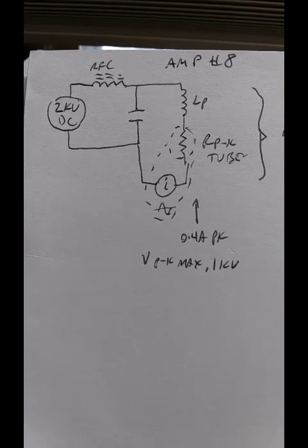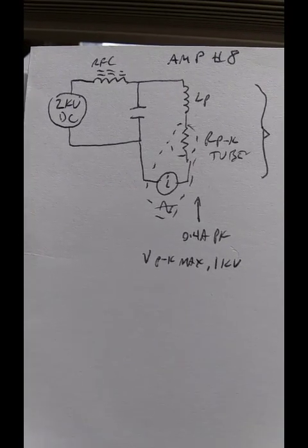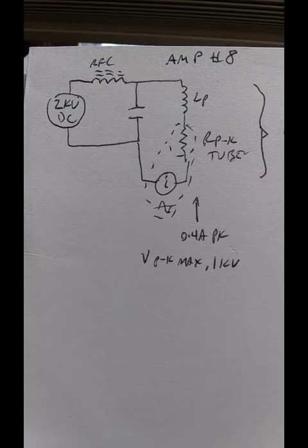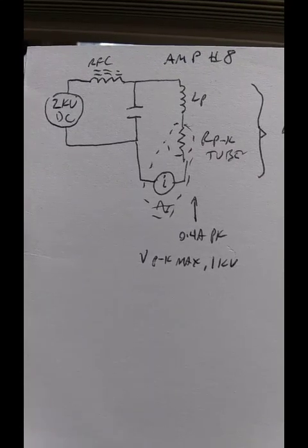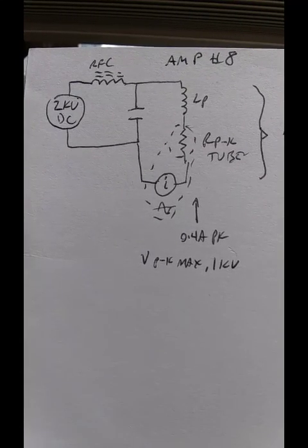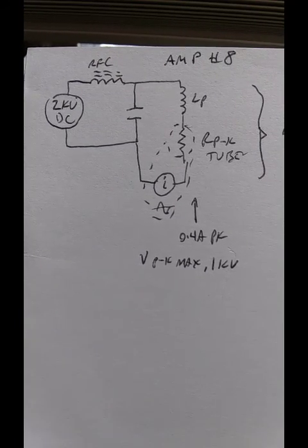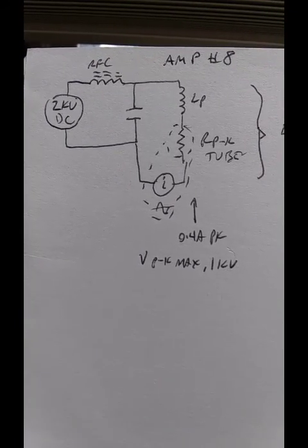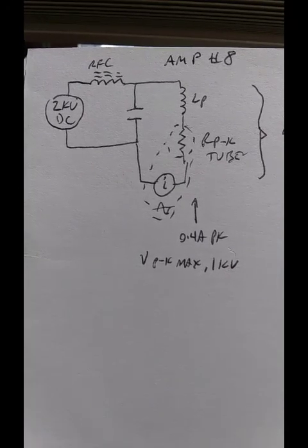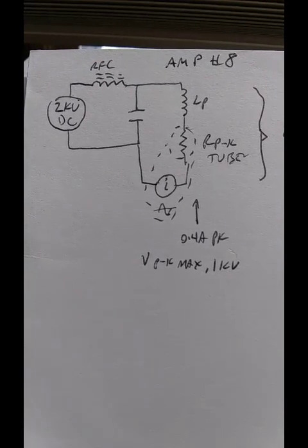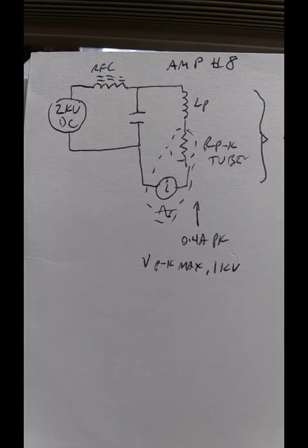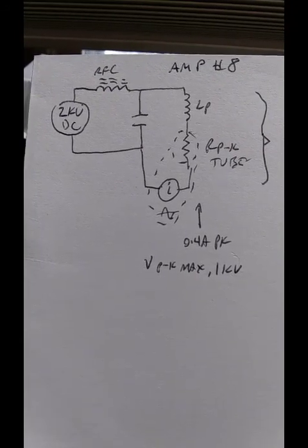And this is maybe a bit hard to wrap your mind around, but it's the inductor that causes a voltage swing. Replace the inductor with a short circuit, the tube will work, but the plate voltage will always be 2 kV, because that's the source. Replace it with an open, there's no voltage or current. So somewhere in between there, that inductor has the effect of establishing the plate voltage, and that voltage is what's coupled in a voltage-coupled amplifier to the output.